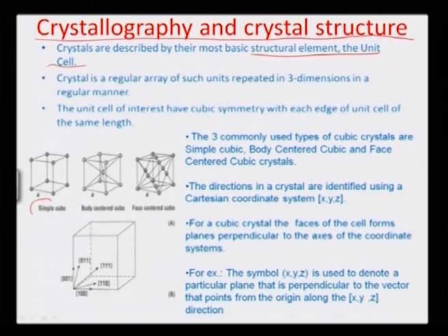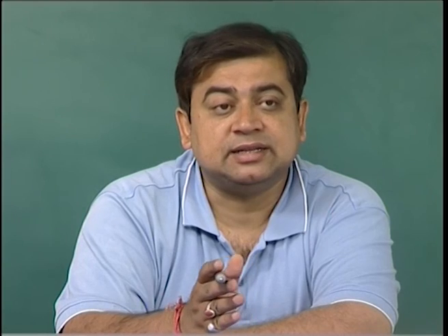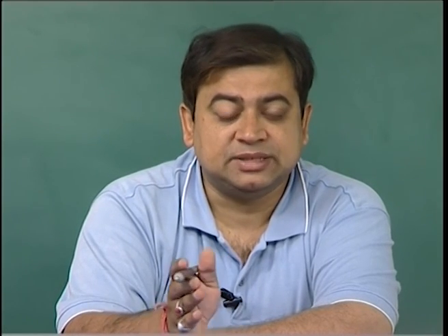So you can divide these into different classes of crystals, like simple cubic, where you can see there are about 8 atoms on the 8 corners of this particular cube; body centered cubic, where you have atoms on the corners as well as one in the center of the whole cubic lattice. And this is what one unit cell would look like, and a repetition of all these unit cells in the 3 dimensions would typically result in what you call a single crystalline material.